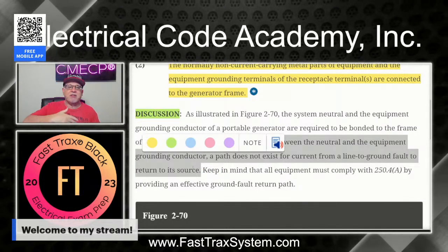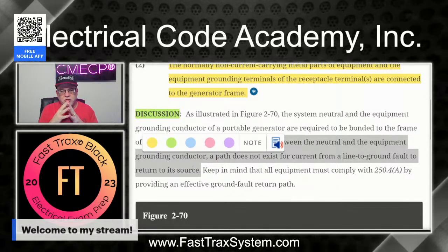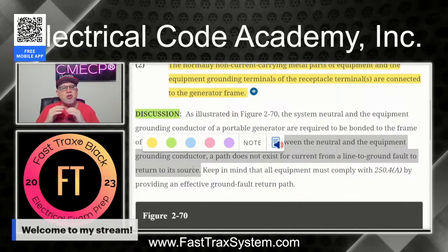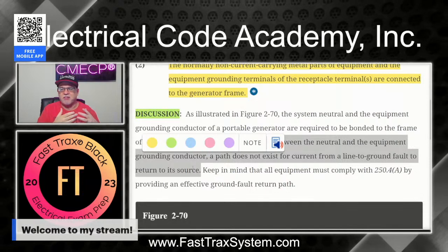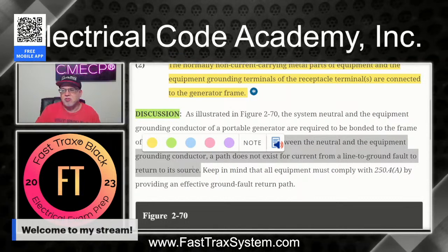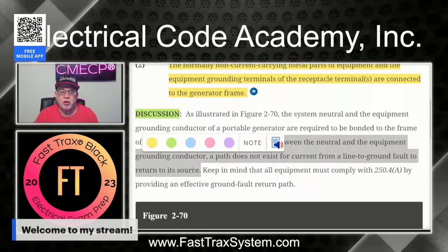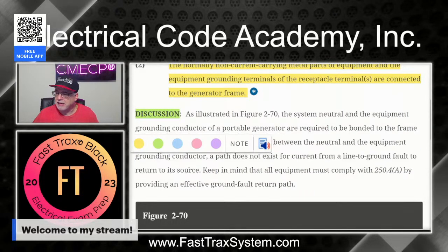Remember, it's trying to get back to where it originates, never trying to get to earth. So if it originates at the generator, the windings, it goes out, serves the load, and everything comes back. It's all trying to get back to the source. So if you don't have that connection from the frame over to the neutral point and something gets energized in some metal parts of the piece of equipment that's plugged in to the generator, or something happens on the frame, if it can't get back to the source, then it's not going to be able to clear an overcurrent protection device. So that could be very problematic, right?